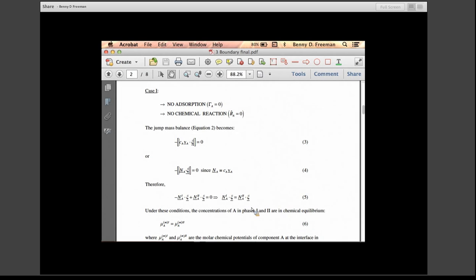So think about it, you've applied this probably without thinking about it this way many times before, right? You establish a boundary condition at a liquid-gas interface, and any liquid that leaves the liquid phase enters the gas phase, right? But the fluxes of the components are matched at the interface. You can also apply that to heat flux at a conductive interface. The heat fluxes are matched at an interface and so forth.